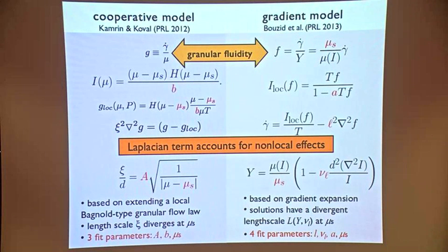non-local effects can diffuse. So this is a non-local length, measured in units of d. This is a functional form that was posited by Cameron and Koval: the square root of 1 over how far you are from the yield stress. There's some magnitude here, and they've played with other functions. Actually, to the 0.6 instead of to the 0.5 tends to work a little bit better empirically, but then the units are bizarre. So you have some choices here to play with, and we've sort of taken the simplest,